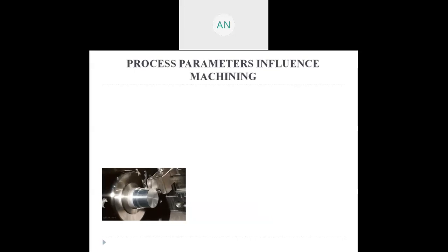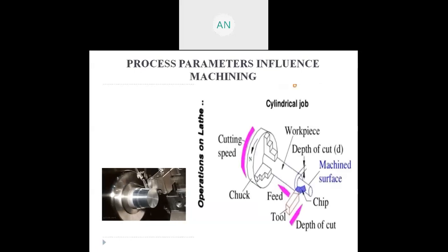So, V T^n = C. You are most likely familiar with the term V T^n = C. V is your cutting speed, T is your tool life, n is an exponential component, and C is your constant. When you expand this equation, the terms which I show in the right image are my cutting parameters when Taylor's tool life equation has been expanded.